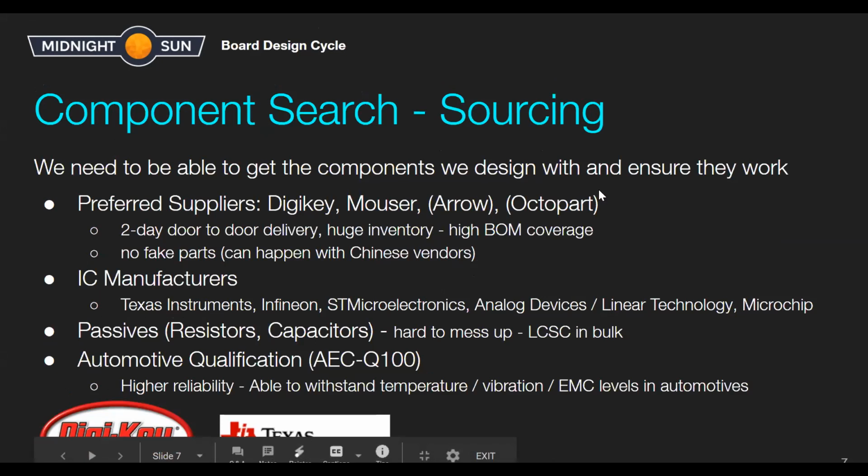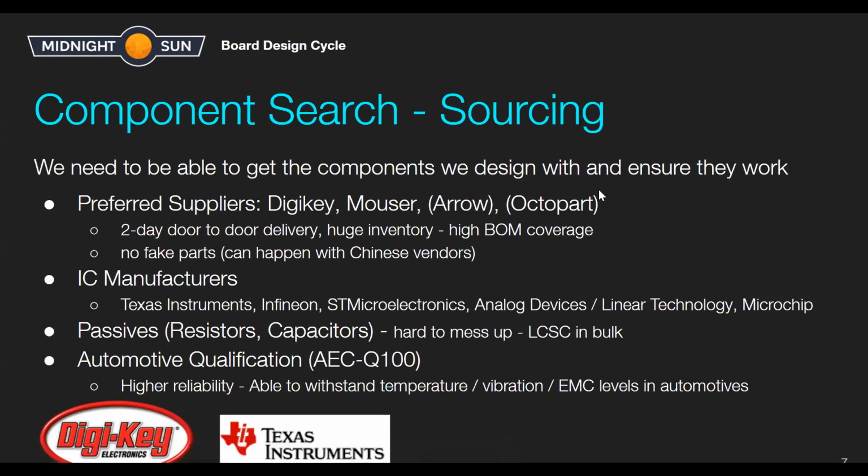A good question from Nita in the chat: has there ever been an incident where we've gotten a fake part on the team? I don't believe so, but I know there are some. If any of you are into lithium battery charging, there's a chip called the TP4056, and that has definitely been copied a couple times in China, with slightly different names, the 4056E, 4056C. They have the same basic functions, but some of their protecting functions and current limiting aren't quite up to spec with the original part. So not for us, but they do exist.